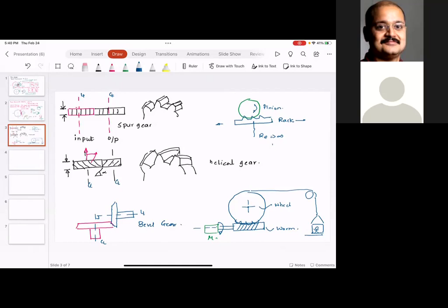Different types of oil have different contact pressure properties. When you select the oil, some oils can support very high contact pressure. Some oils cannot support such high contact pressure, but they have better heat dissipation. So you have to balance these factors together and finally come up with the oil grade. And the temperature affects the viscosity, so sometimes you use a different SAE grade in summer and a different SAE grade in winter.